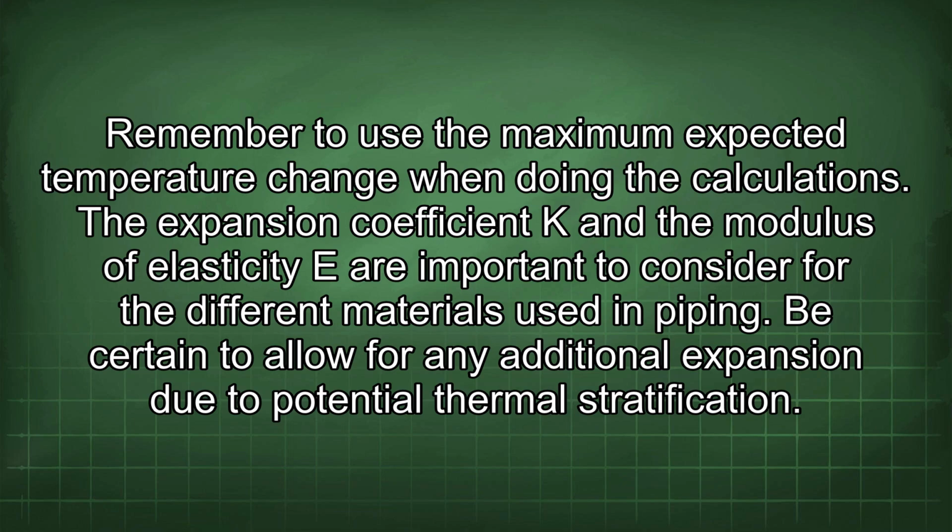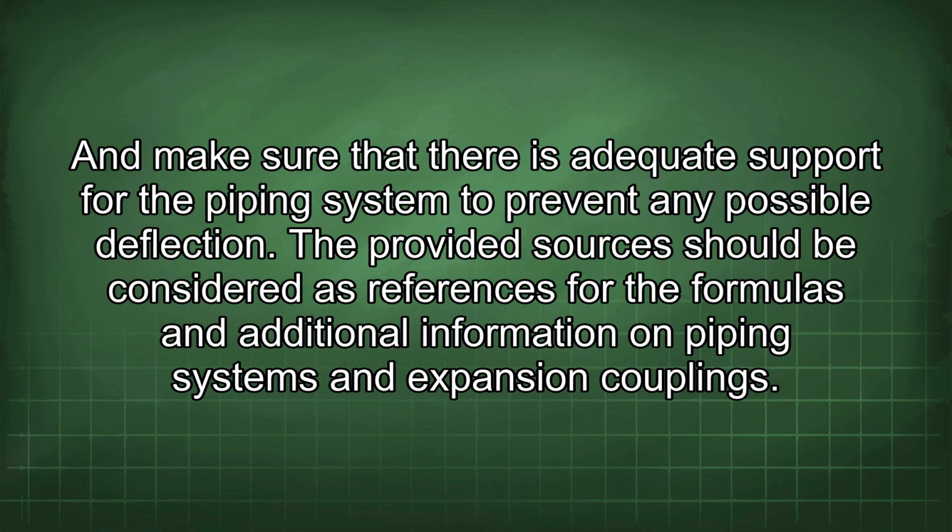piping. Be certain to allow for any additional expansion due to potential thermal stratification, and make sure that there is adequate support for the piping system to prevent any possible deflection. The provided sources should be considered as references for the formulas and additional information on piping systems and expansion couplings.